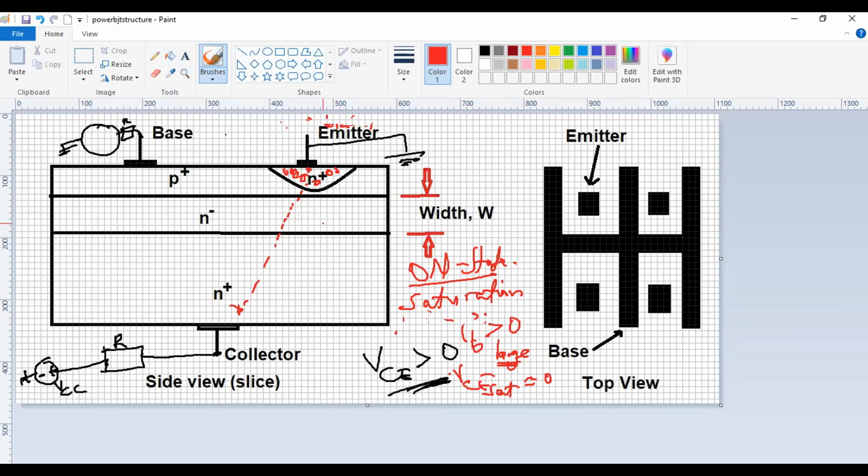So basically what is happening is that now, if I get this to become forward biased, then I can have electrons flowing from the emitter and crossing this boundary. You remember, for these devices, that boundary is designed to be small enough that in addition to being attracted this way, most of them, because that gap is small, will be attracted down here.